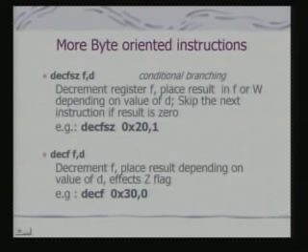What is the motivation for designing such instructions? Because similar instructions you will find in other microcontrollers and processors targeted for embedded systems. This increases what we call code density. That is, instead of using 2 instructions, that is one instruction to decrement and then jump, you are using a single instruction. So, the number of memory locations that your code would occupy can decrease. If it decreases, what does that mean? You require less memory, and obviously when you are working in an embedded system, you try to work with less memory, and less memory would also imply less power consumption.